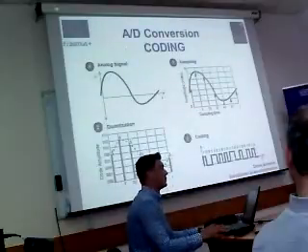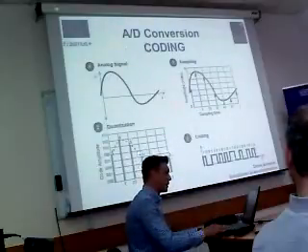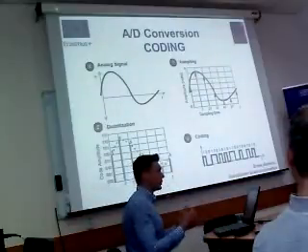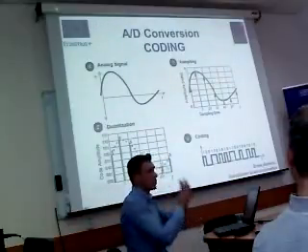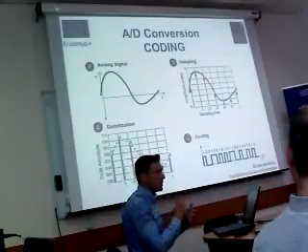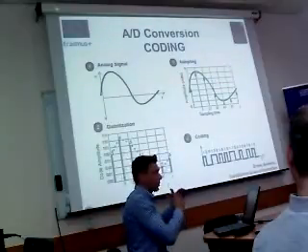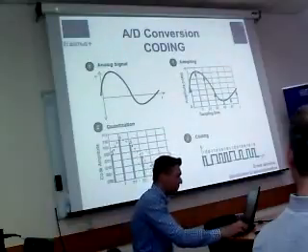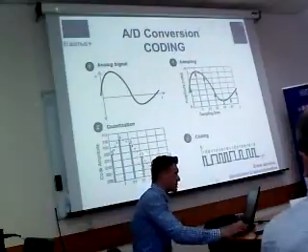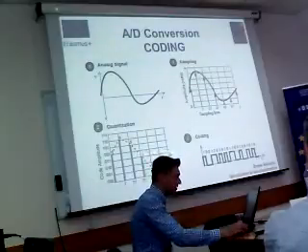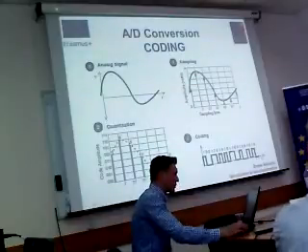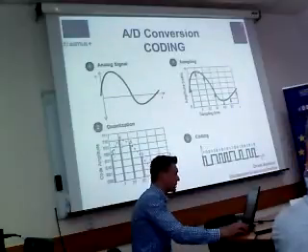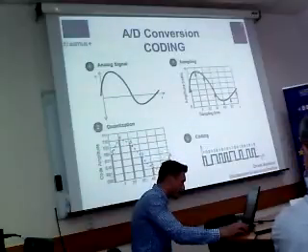Then we are moving to coding. When we recognize the levels and put each probe to one of the recognizable levels, we've got each probe on a level which we can recognize. That's why here is the whole process again: from analog signal to sampling, so taking samples, then quantization, then moving each sample to one of the recognizable levels. These are recognizable levels.